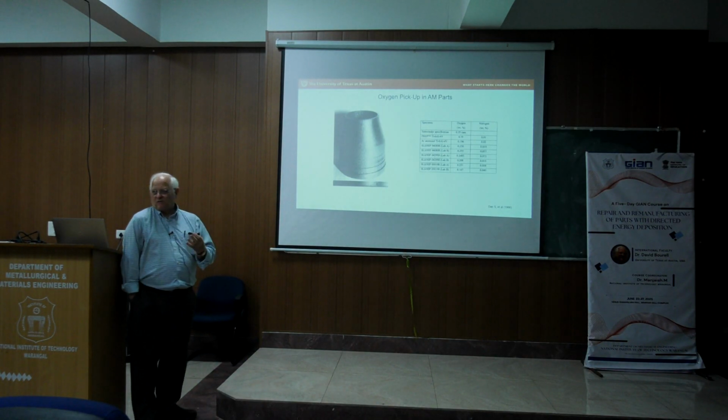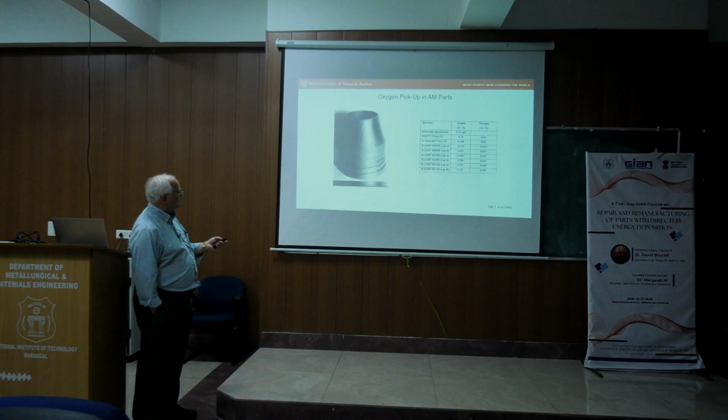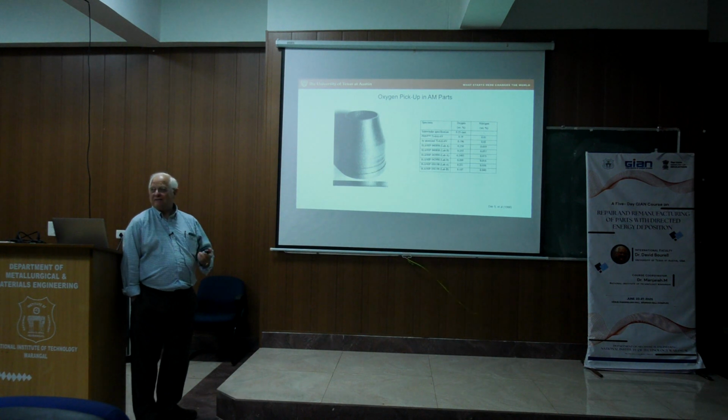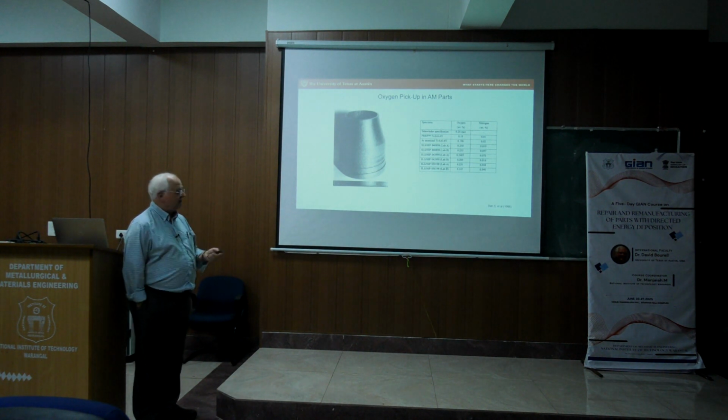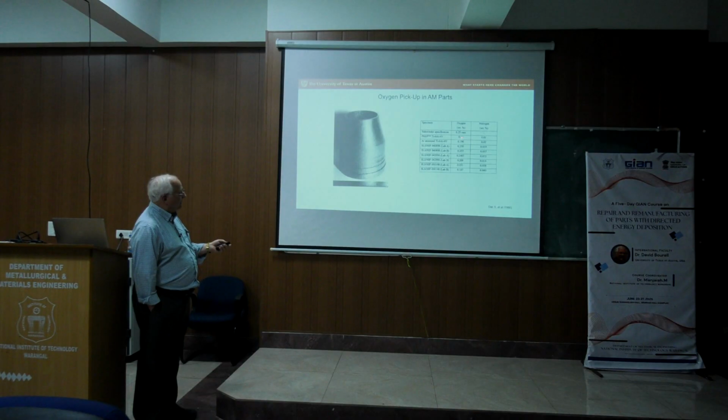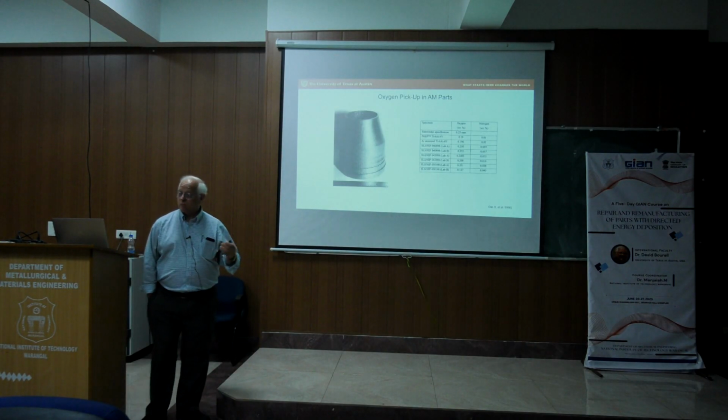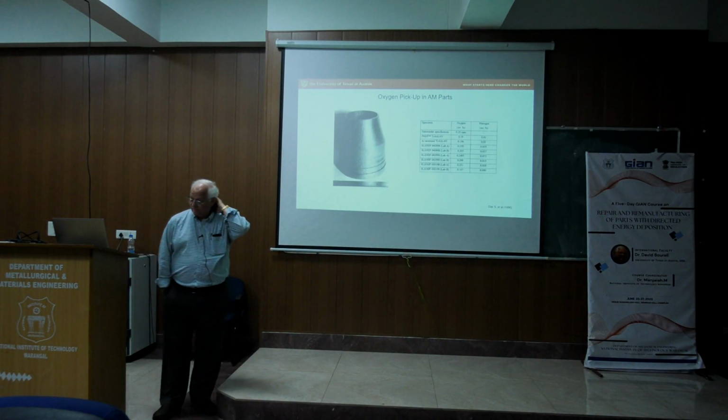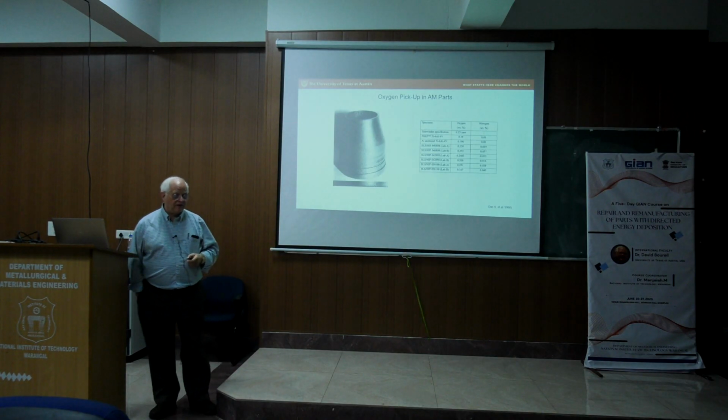Basically, it makes a very nice spherical powder. But the feedstock itself had 0.19% oxygen. And so we were basically only adding about 0.05 or 0.06 percent of oxygen.